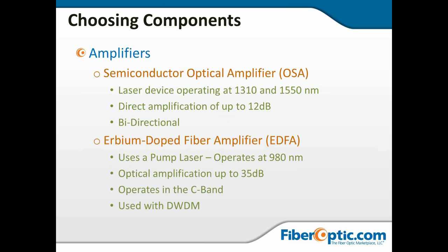Now, amplifiers. There are a couple of different options for amplification. The semiconductor optical amplifier, or SOA, is a laser device. It operates at either 1310 or 1550. It is a direct amplification up to about 12 dB, and it is bidirectional.